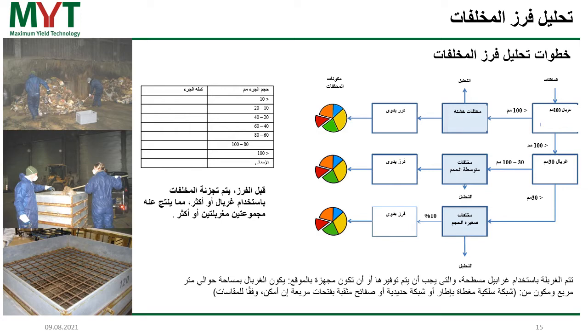And then, as you can see here in the pictures, you put the waste on the first screen, and that gives you the coarse waste fraction, which is then later sorted by hand. Then between 100 and 30 millimeter, you get the medium waste fraction, which of course is also sorted by hand.